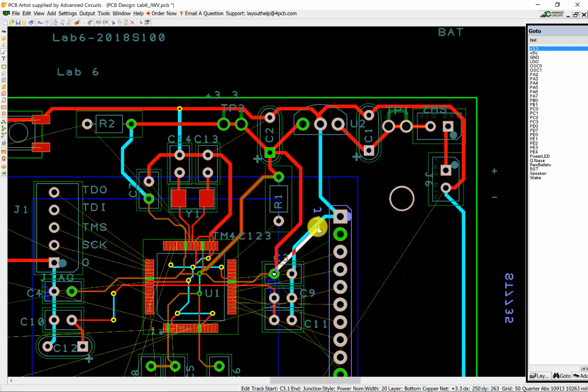And on this circuit, that's what the LDO is. That is the 2.5 volt power supply running the architecture. The I/O runs at 3.3. The architecture runs at 2.5. But don't tie 3 volts to 2.5 volts. That's fire. That's bad. Okay.